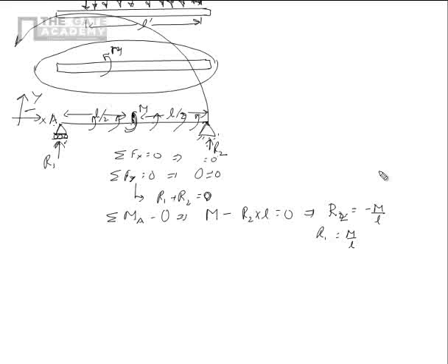You can apply the moment anywhere and you can figure out that the reactions remain same, M upon L and minus M upon L. These reactions do not change by changing the position of the moment. Now let's get back to the distributed force.